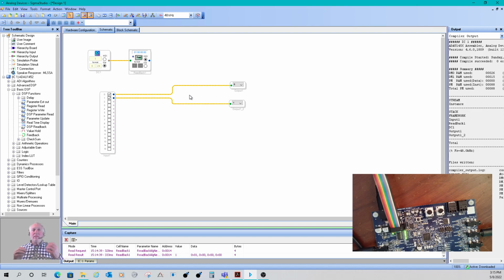Likewise, by the way, if you have a controller, you can always just send and quickly read back a memory location. Set a register, read it back, see if you can read and write from the part. Start simple. And don't forget to set it into SPI mode. You need 3 writes to set it into SPI mode. So anyhow, now we're looking at the audio path.